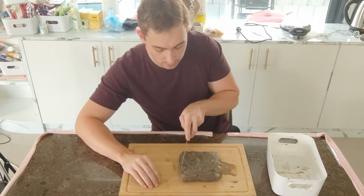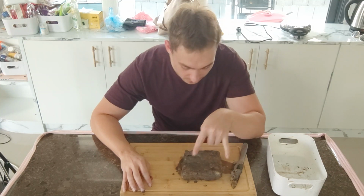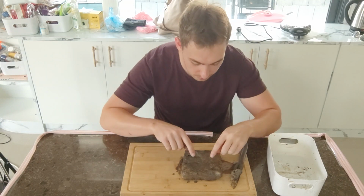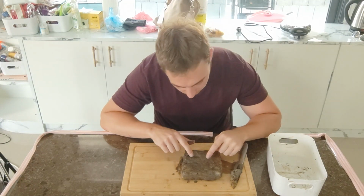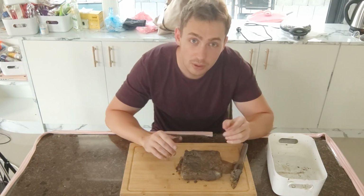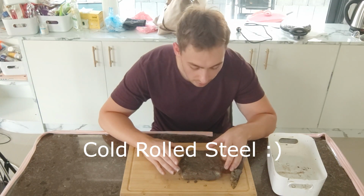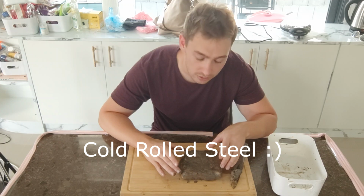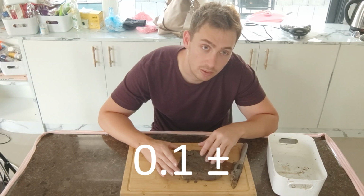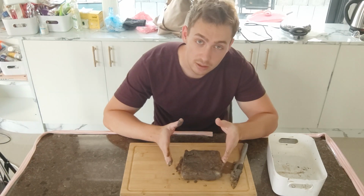So imagine, I'm going to exaggerate a lot, the dimension right here is of course smaller than this one. So one way to do it: let's say you put the tolerance that there has to be symmetry of the hole from this to this side. Then we need to machine each side if you want that. Or you could choose to buy cold rolled steel with higher quality production, and you would actually have somewhat a plus minus 1/10 of a millimeter. So that's another option. But let's say we have hot rolled steel and it is not straight.